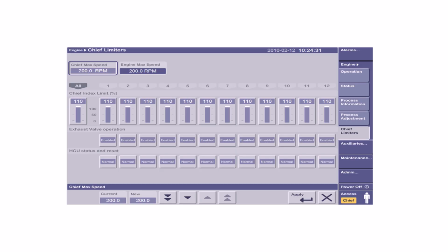For example, you can say exhaust valve operation can now be enabled or disabled. If you cut off the unit while the engine is running, the exhaust valve keeps opening and closing. If you want, you can keep the exhaust valve closed, or keep it in the open position. But that position has to be set manually when the engine is stopped. The tools and all are given in the manual. The exhaust valve can be manually kept open. There is a method, but I am not discussing it here.